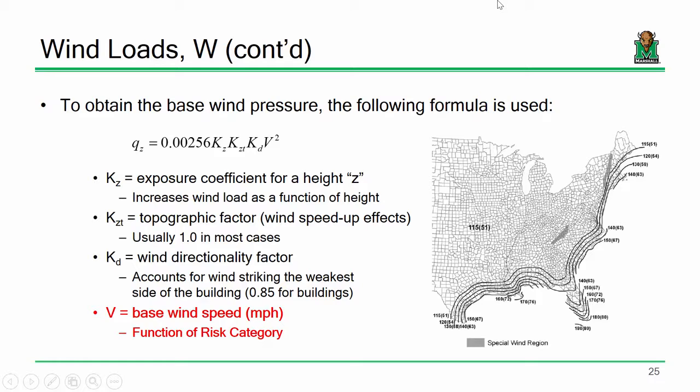Think about it: when we look at seismic forces, what we're essentially doing is asking ourselves how many G's, if you will, the building has to respond to. So imagine if I took Smith Hall and just picked it up and held it right there. That building would be experiencing 1 G at that point, because it's just subjected to its own self-weight.